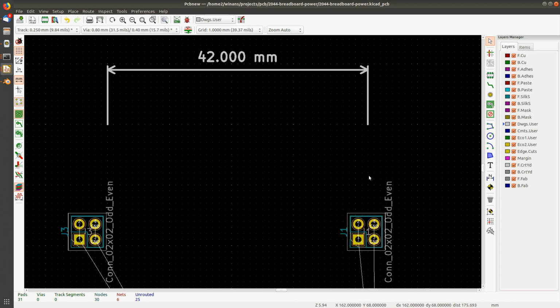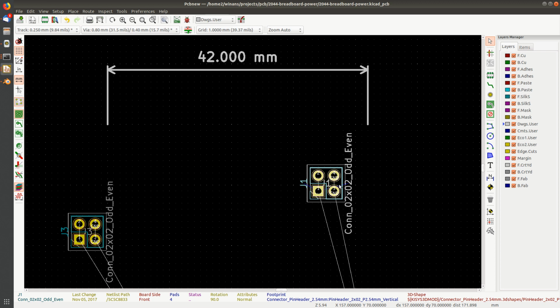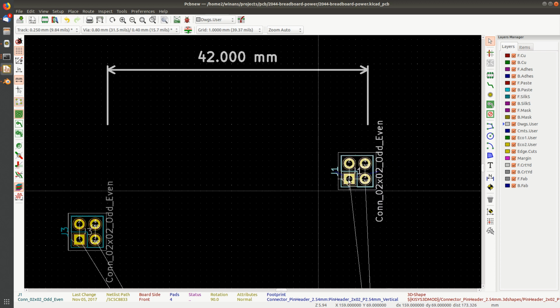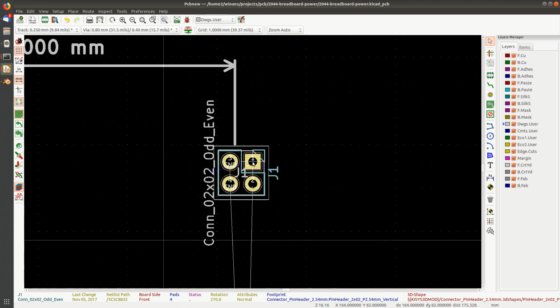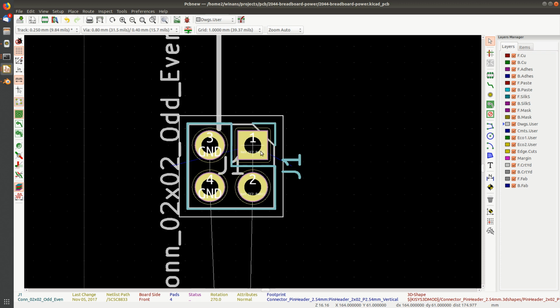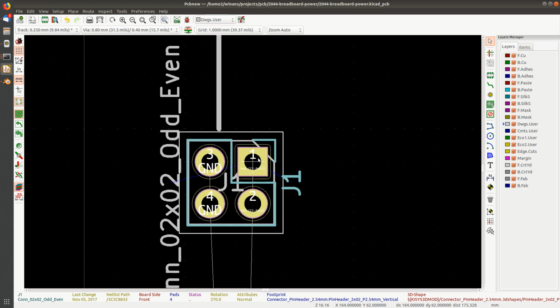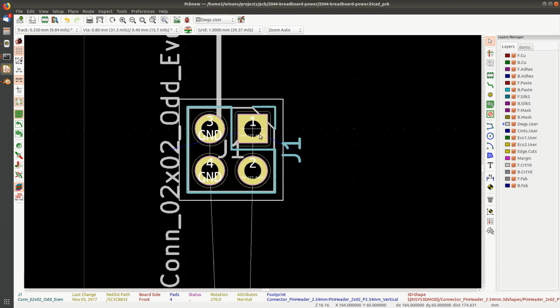I've grabbed it. Sometimes when you grab a part and you move it around, you're not moving it based on what you want to hold on to. Let's say I'm going to rotate it around this way. If you see what's going on here, and I'm in the snap to grid mode, I can't get it to go where I want it to go. When that happens, if this is really the orientation I wanted this part to be in, I'd have to change my snap to grid dimension to a higher resolution to give me more options until I can get that right in the middle of that pin.